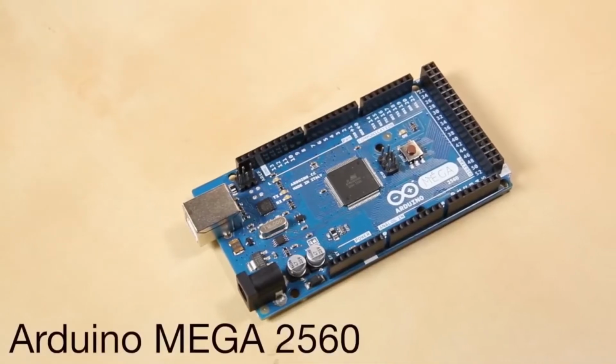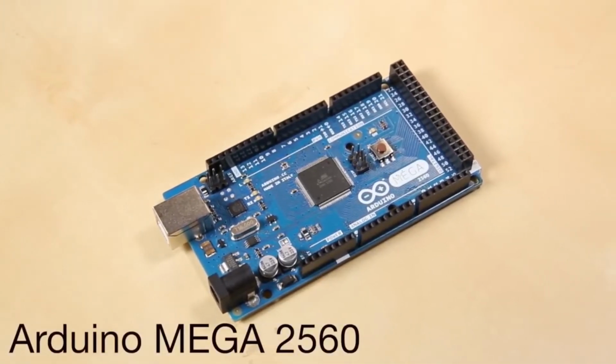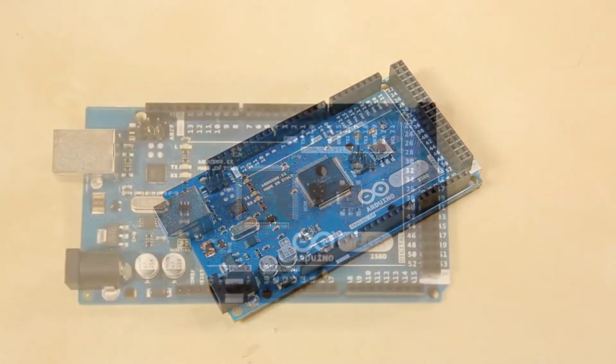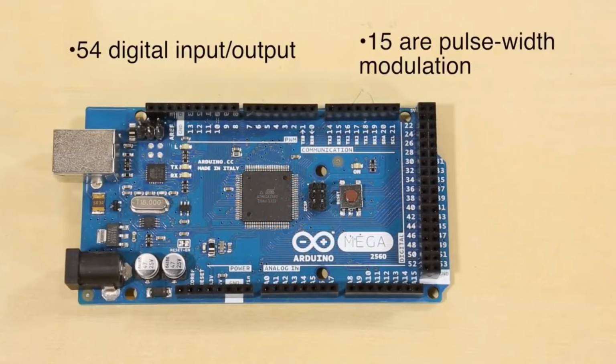External, non-USB, power can come either from an AC to DC adapter, wall wart, or battery. The adapter can be connected by plugging a 2.1 mm center positive plug into the board's power jack. Leads from a battery can be inserted in the GND and VIN pin headers of the power connector. The board can operate on an external supply of 6 to 20 volts.